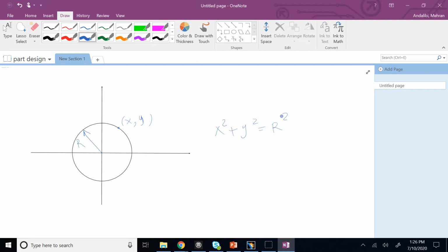Fine. Now, we can draw a circle in CATIA, no problem. We can define ellipse, we can define other function. But now, let's say I want a kind of curve that does not exist in CATIA. Like what? So I cannot draw it using those sketcher commands, right? Like what? Like sine function. So if you have something like this, okay, so here y is sine of x. Well, how would you create this kind of curve in CATIA?